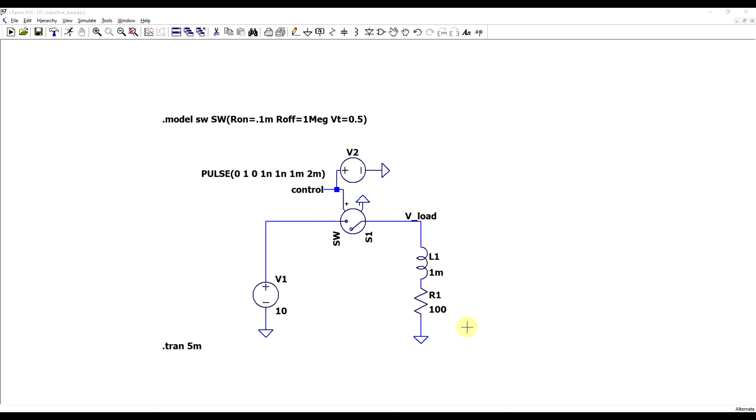Hopefully now the problem becomes a bit more clear. Real-life loads usually have some reactive part, either inductive or capacitive. So when designing switch circuits, it's important to keep this in mind and make sure the switch is never exposed to an out-of-spec transient. Let's now look at some protection methods, and to see how they're supposed to work, let's also simulate them. Let's start with the inductive load.